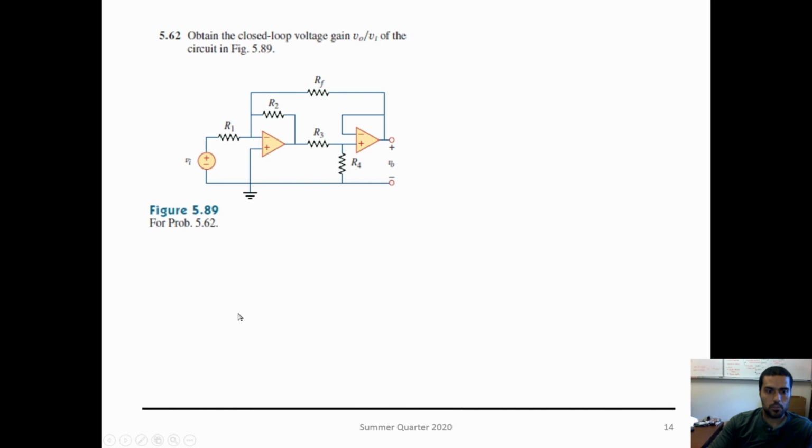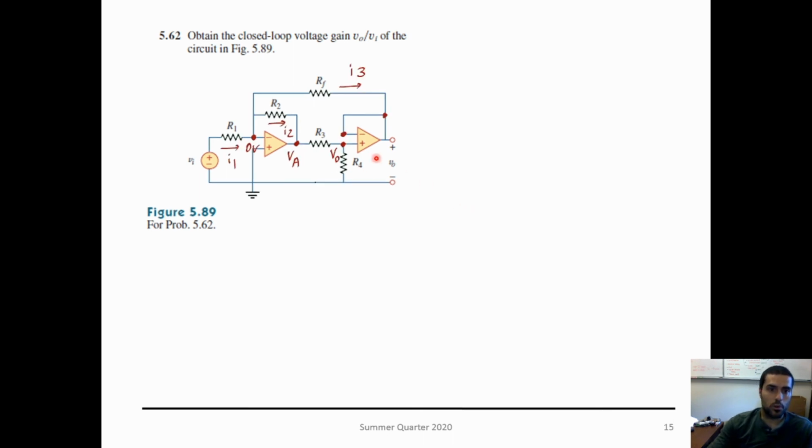All right, our last op amp, probably the most confusing one because we have kind of 2 feedback loops here. We have one over here and another one feeding back over there. Again, no need to freak out. First thing, we put what we know. We know that VP is equal to 0, VN is equal to 0. And now here it's the fun part. We have Vout feeding on your VN, so that point is going to be equal to Vout.